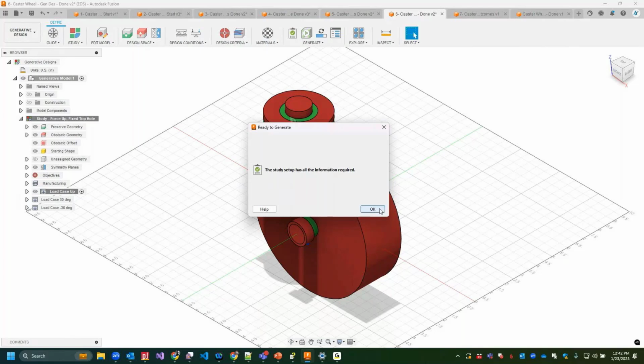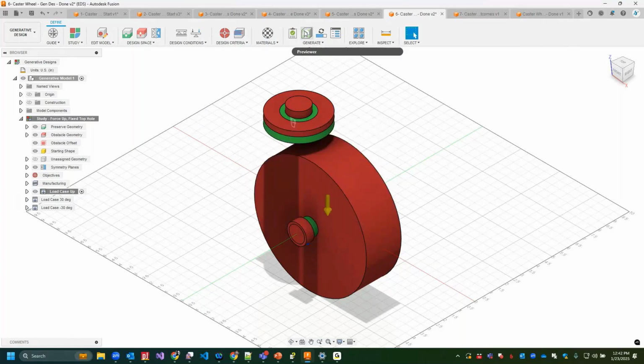And I've got a slide on this as well, but we also have this previewer too, and the previewer will allow you to preview what generative design is going to do. This is a free option to be able to preview this. It's not going to be as refined as what we get from actually generating the outcome and seeing the finished outcomes there. It's a local simulation, generating all local here. It's going to take those preserves and that obstacle geometry and show a preview of what it thinks it's going to do in the very beginning. It's really, really rough.